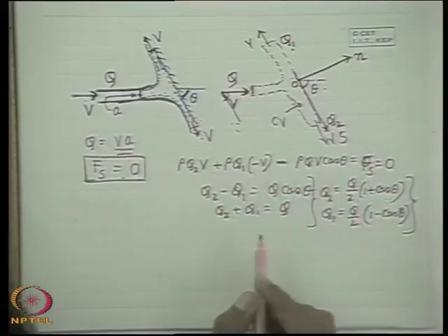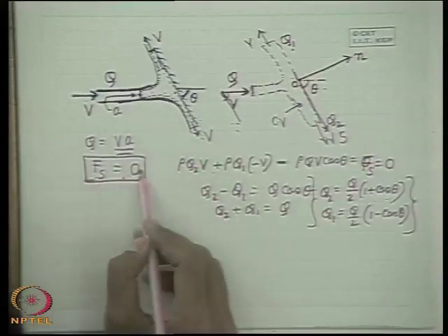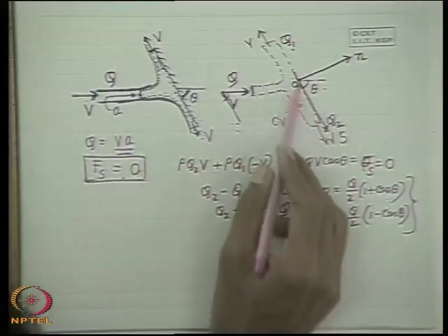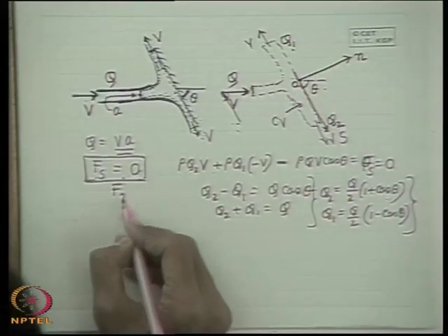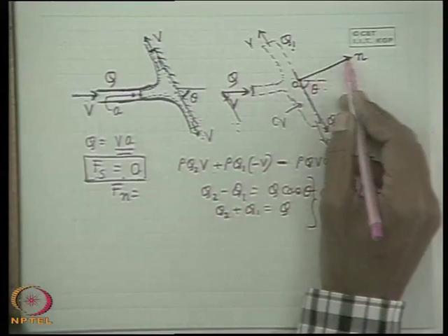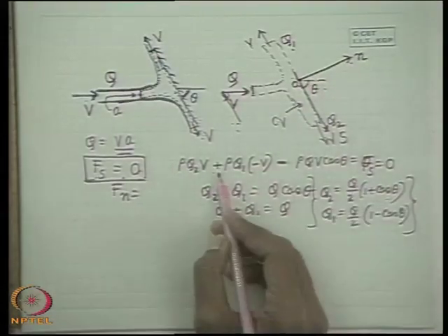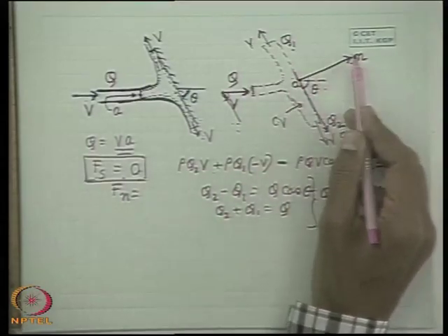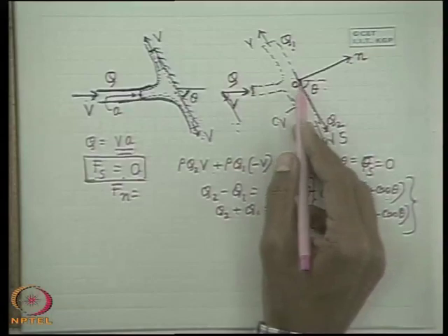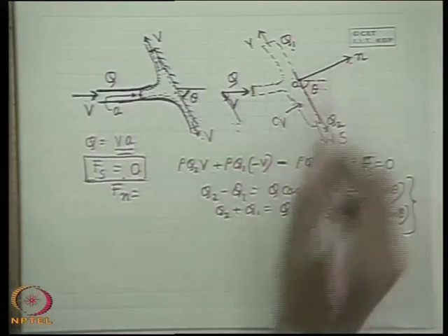Now to find out the force, from the basic physics, we have already defined that Fs is 0. So if we choose two axes like that, OS, ON, we can tell the net force acting on this control volume is only in this direction, and that is equal to Fn. This Fn we can find out from the application of the momentum theorem with respect to the control volume along the ON axis. Let us write it. That means the net momentum efflux from the control volume along ON.